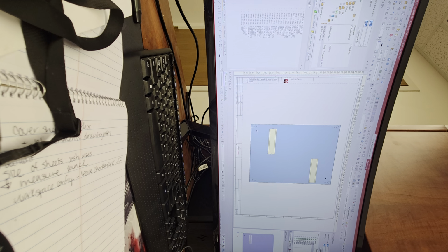So if you say I want to be 3 inches from the bottom as an example, you can type 3 inches and you say align to bottom, right? So your reference is bottom in this case, but you are 3 inches from the bottom. So this is one way of using this placement tool on a quick alignments perspective.